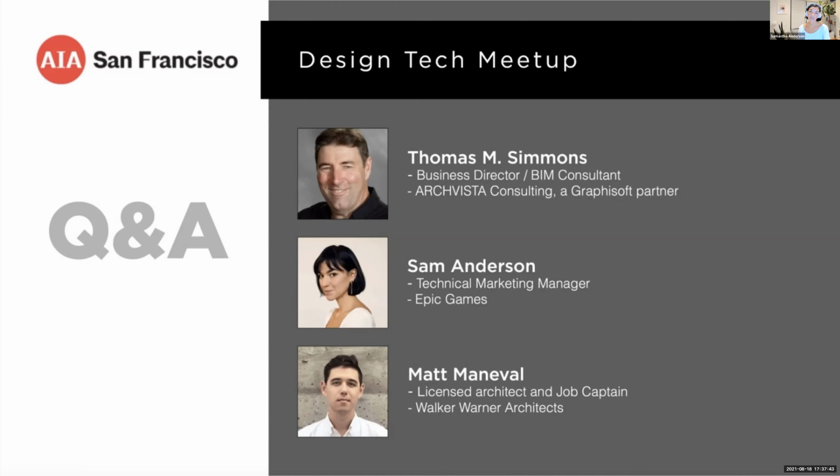So there's a few different ways that you can bring in your model. One of the ways is with an FBX. You can also bring it in with the Datasmith direct link, which is what I was referring to. That is going to save your materials in there, so you'll be able to bring them in as is, and it's going to translate your materials to PBR materials, which is physically based rendering materials. That's what the Datasmith file format and plugin does. It's translating all of those JPEGs and bump maps that you have into Twinmotion accessible files and materials. But there's also a huge library of materials that you can use in Twinmotion.